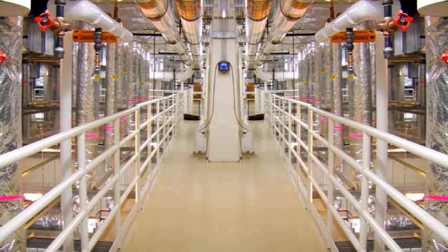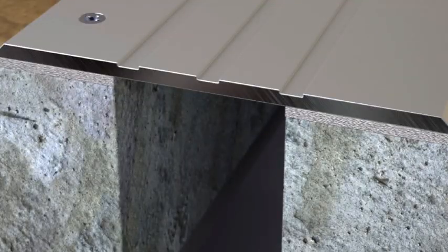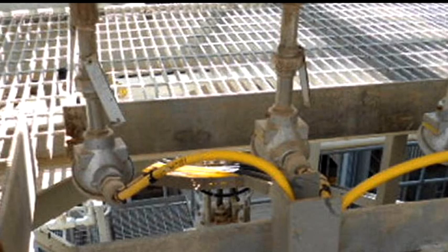Regardless of height, open-sided floors, walkways, platforms, and/or runways above or adjacent to dangerous equipment must be guarded with a standard railing and toe board. All floor openings measuring 12 inches or more in smallest dimension should be covered or guarded to prevent a person from falling or stepping into the area and/or materials from falling into the area.